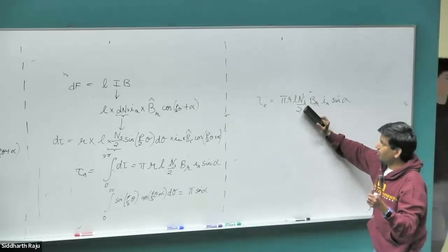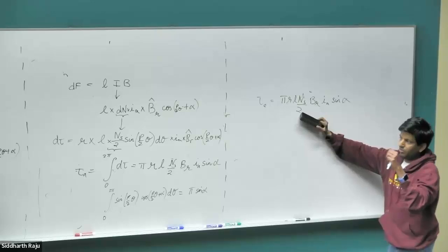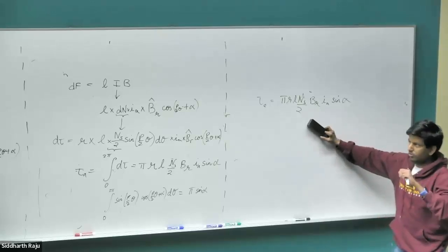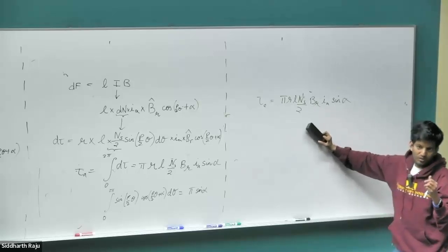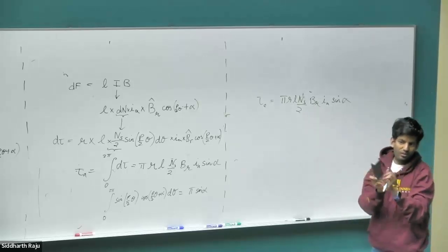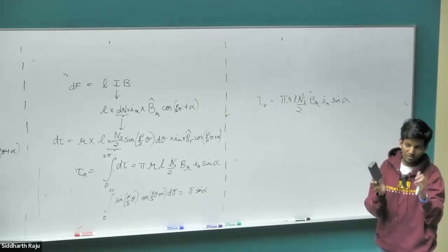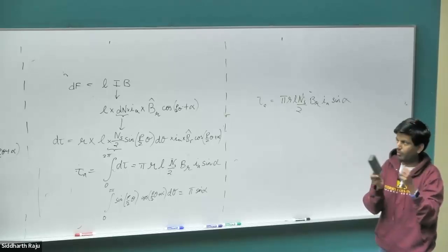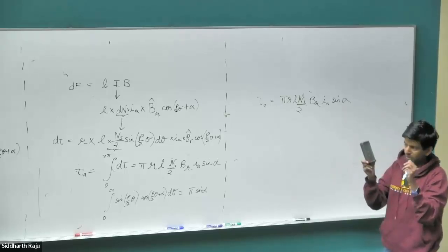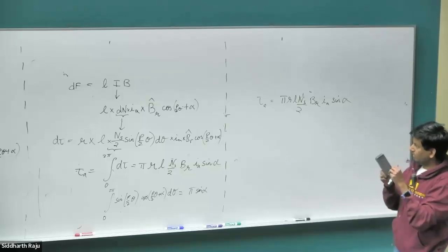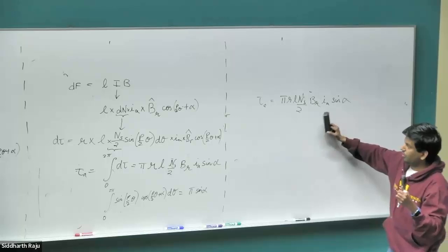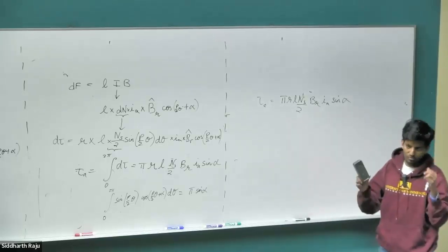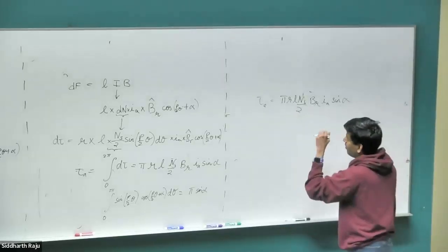But increasing the pole count means that the flux density concentration over any particular pole phase would reduce by half if you double the poles. That will allow you to either double the number of conductors or shrink the yoke length. You can increase the torque and power density of the motor by reducing the core size as well as the yoke size, or you can double the conductors and increase the torque that you can generate for the same motor structure. Alright, so that's why you would go to higher pole count.